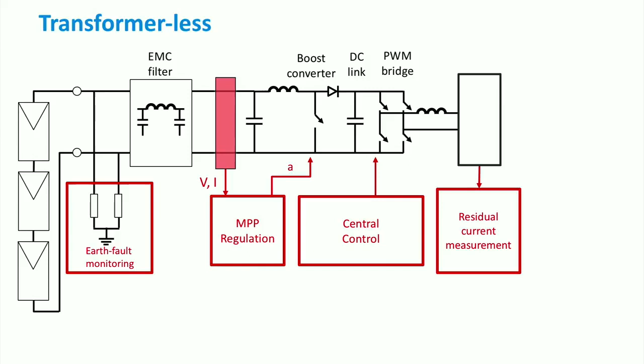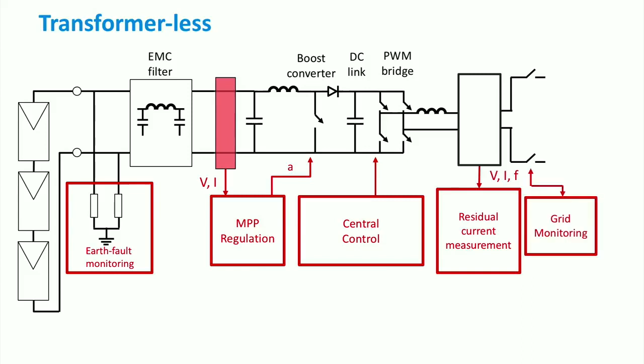After this part, circuit breakers are usually present in order to shut down completely the inverter in case of overvoltages or voltage dips on both the PV and grid sides. The breakers are linked to the grid by means of a grid monitoring system so that they can be activated when faults occur. In this case, voltage, current, and frequency are the parameters normally included in the data exchange.